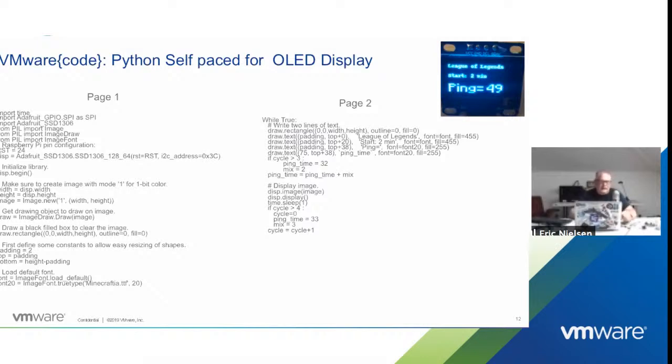And then I'm going to make a display object. I'm going to call the Adafruit library, the SSD 1306. That SSD chip will run in 128 by 32, or 64 by 32 mode, or 128 by 64. So basically low res or high res. 128 by 64 is what I'm going to run in. I'm going to run it high res. I have to pass in the pin numbers, the way I'm going to address the pins, and I have to pass in the I2C address, which is 0x3C.